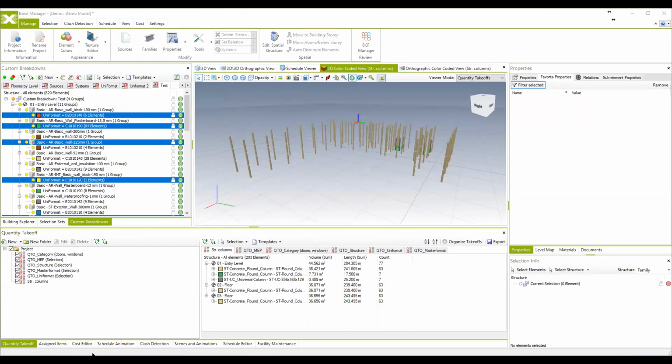And you see different sheets in our quantity takeoff Excel sheet. The first one is the tile report, which includes all these elements visible, graphically presented on your screen with all these quantity properties that we provided when we created our quantity takeoff.